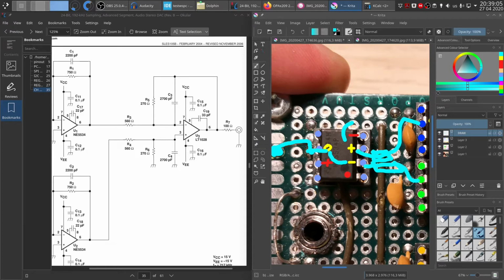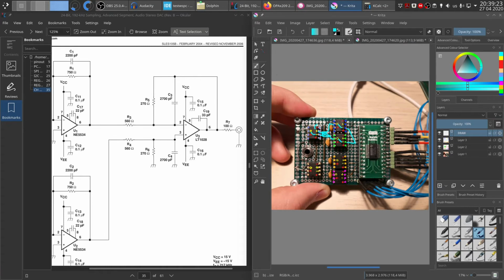So if we have a spike on the positive input and the negative, and this minus this is 0, therefore the common mode noise, so the noise that is present on both lines, will be cancelled out. I will also probably include these images in the GitHub, where all the code and these images will be available, so you can look it up yourself as well, so you won't have to keep going back to this video. So now I see 20 minutes, so this is the hardware actually done. This is everything. Also the second channel is a copy of this, so it's exactly the same.